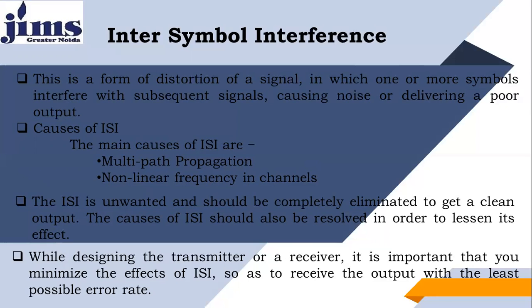The output of the transmitter is a series of symbols, and these symbols propagate through a channel. As the signal progresses, these symbols are broadened, sometimes spread. Each symbol has its own time period, its own symbol period. But sometimes a symbol interferes with the neighbor symbols.